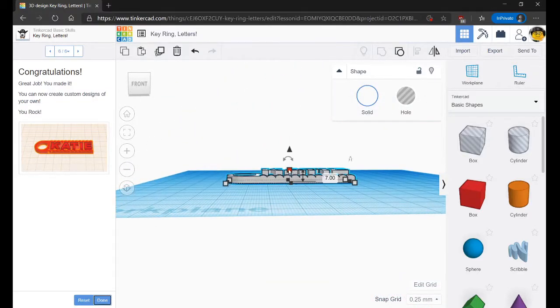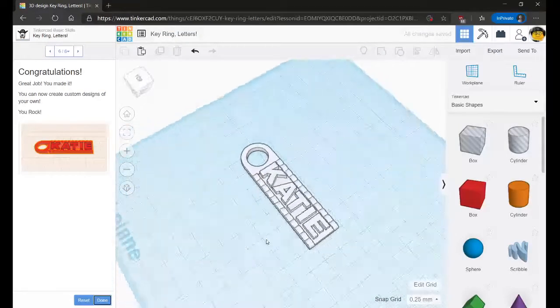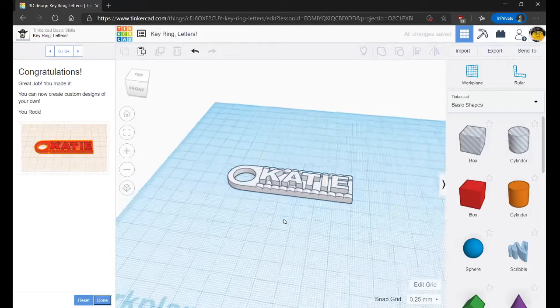The 3D printing software will slice it and create layers, and when you have it as one entire object, it reduces the chance of any errors happening in between those objects. So you always want to try and group it before printing.